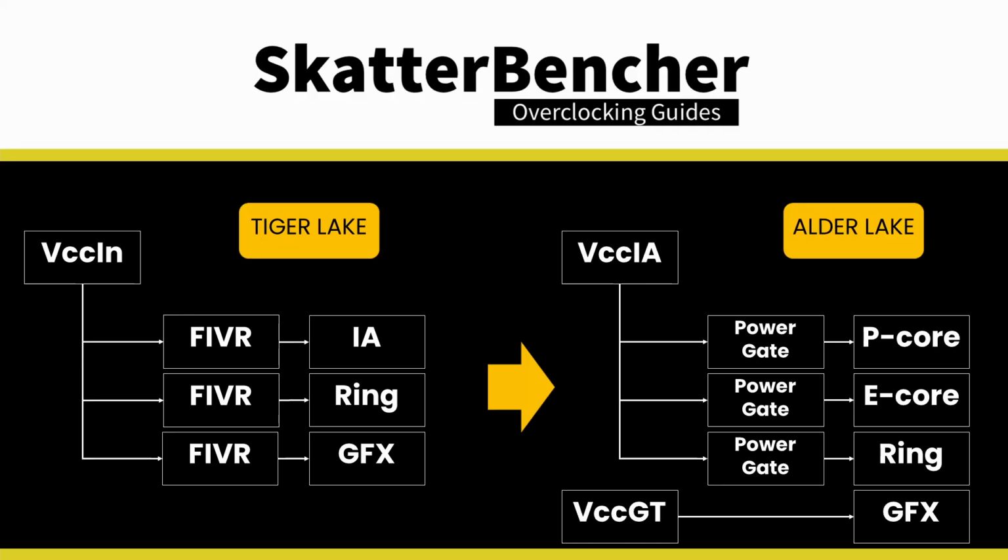To make a long story short, an Intel CPU has power-saving features that allow certain parts of the CPU to shut down when not in use. On Alder Lake, each P-core and E-core cluster has a power gate which allows for enabling or disabling of the cores depending on the current system load. From observation, it seems that the MSI BIOS is loading one P-core and none of the E-cores. This will be important information when we try to figure out the E-core VF curve later on.